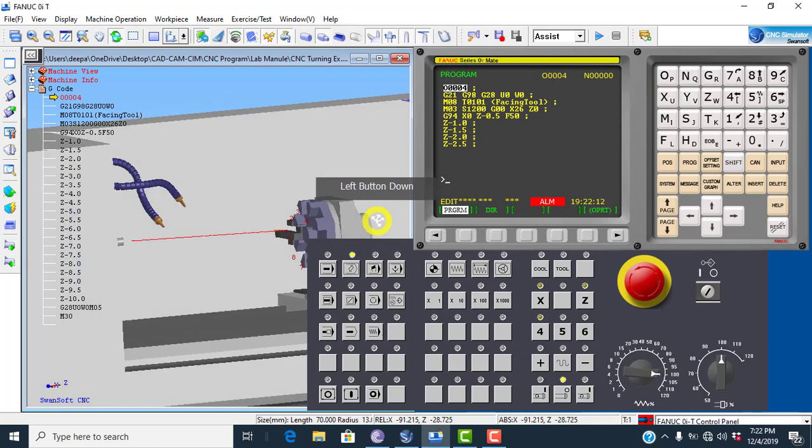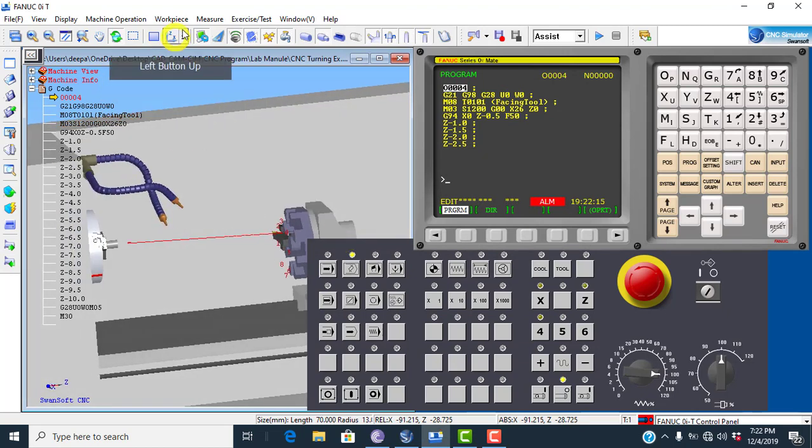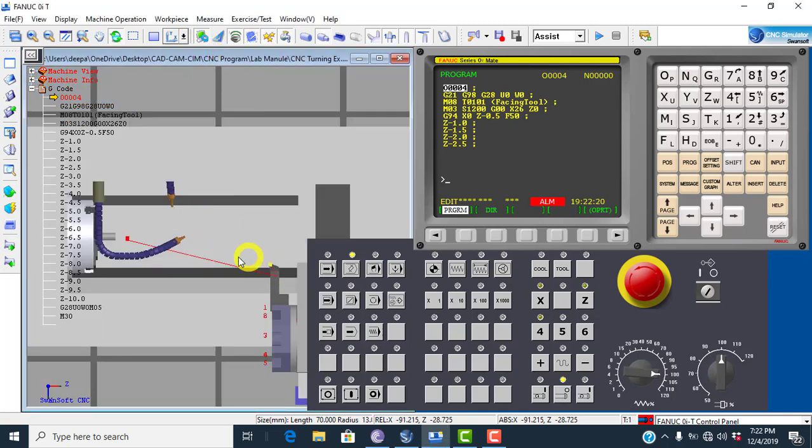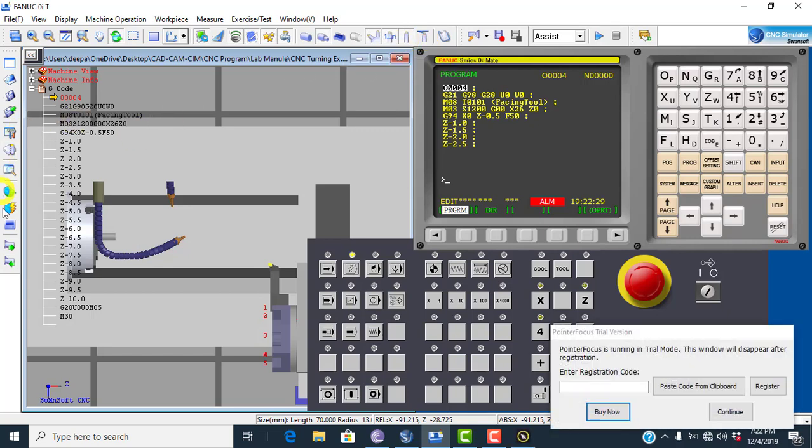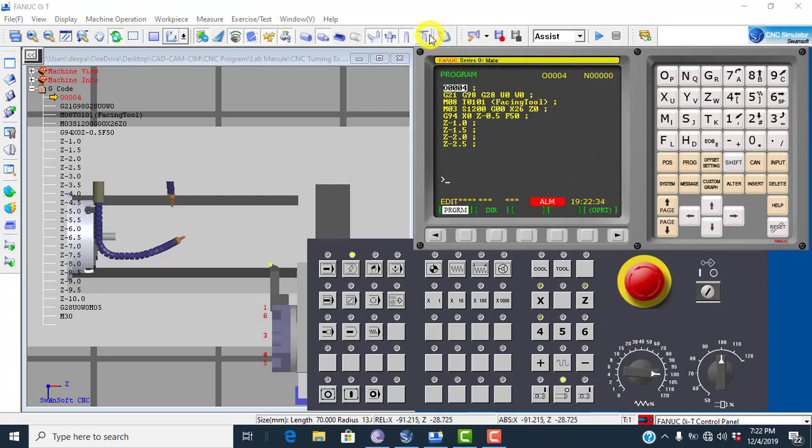Okay, now you see the tool is available here. We can see this from this top position. So our tool is available here and the workpiece is here. Now according to the trajectory of this program, the trajectory you can see from this. So presently the tool is not properly offset. Okay, now after setting everything, you have to bring your tool to the reference position.